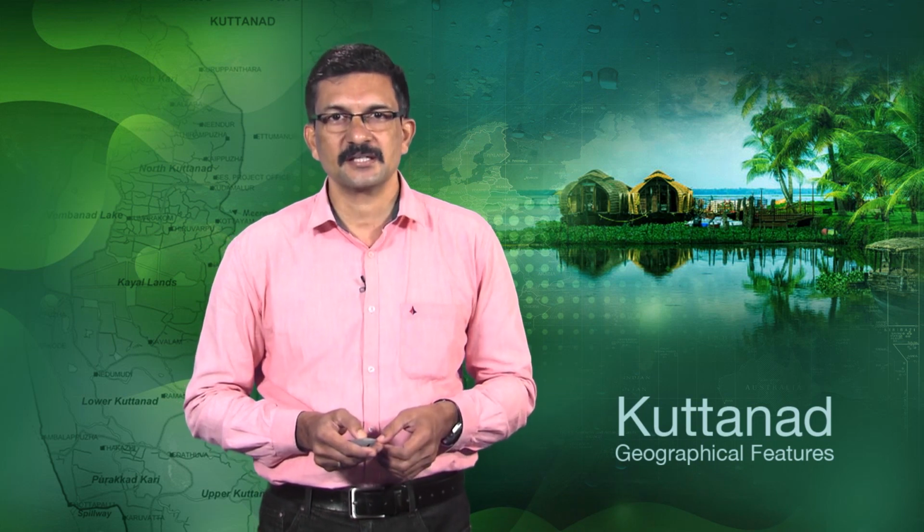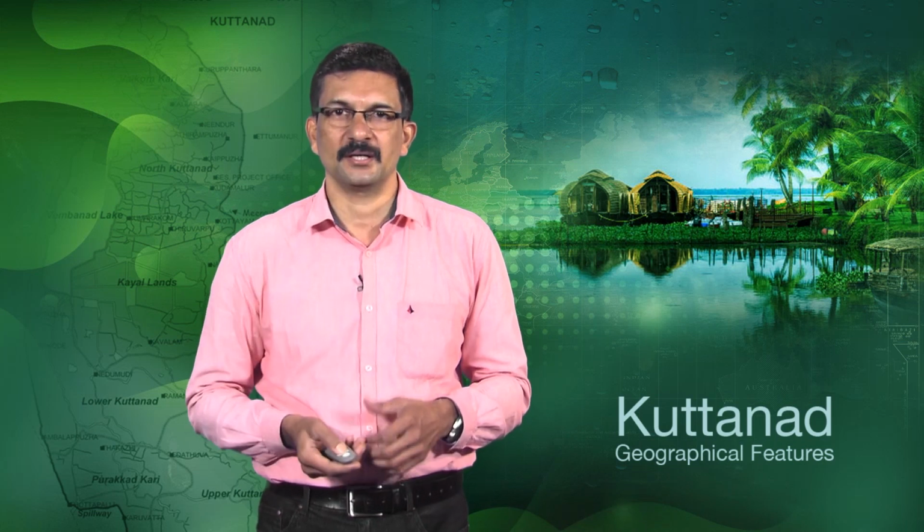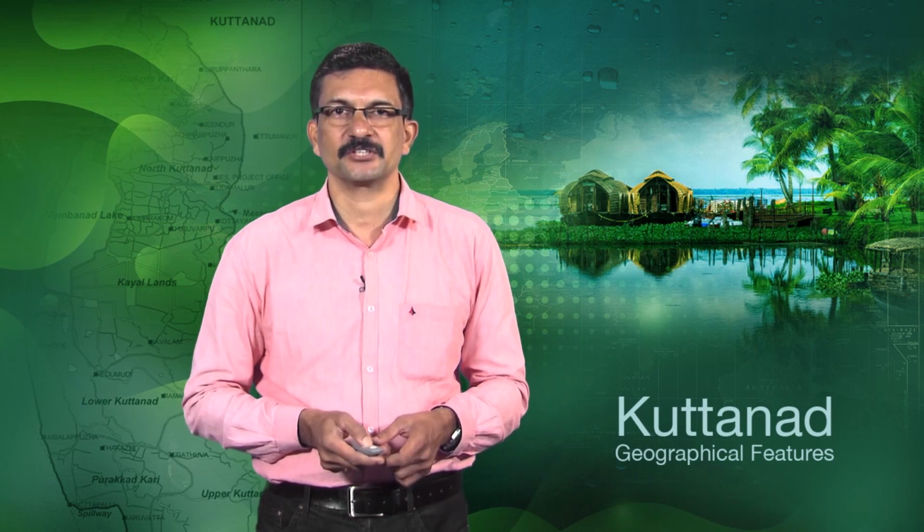So these are the salient features of that particular case study. Random rubble masonry foundation was constructed in the site. The foundation was tilted owing to natural actions over many years. Corrections to the foundation were done through connected concrete columns and soil stabilization. We have done bamboo soil stabilization also in the site, wherever we had to construct new extensions in the building. Loads of the superstructure were distributed to the foundation according to its load bearing capacity. So these are some of the salient features of that case study.